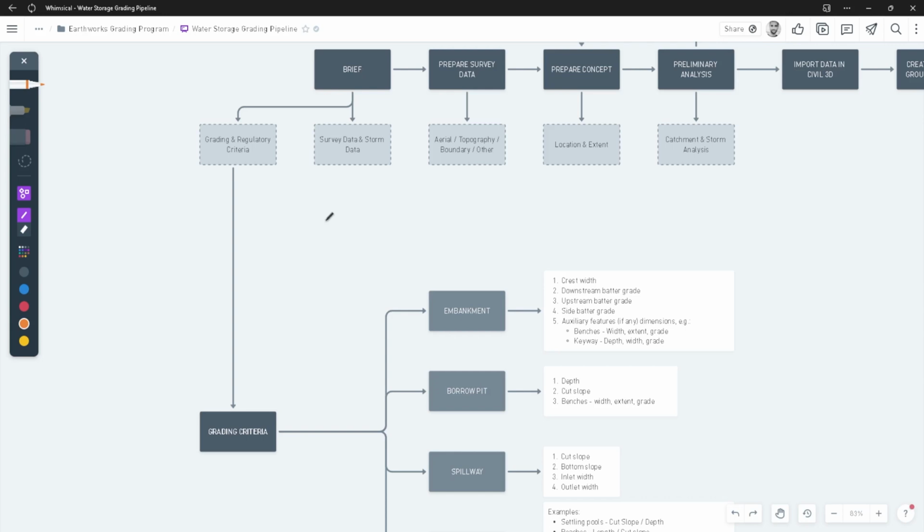And you cannot just afford to work with low resolution data, unfortunately, because when it comes to volumetrics, the way volumetrics are calculated is based on the accuracy of the vertical data, especially, but also the horizontal data. They work together. And if that data is incorrect, it's going to be reflected in the volumetric analysis, which in turn is going to be reflected in any costings that you derive from that analysis.